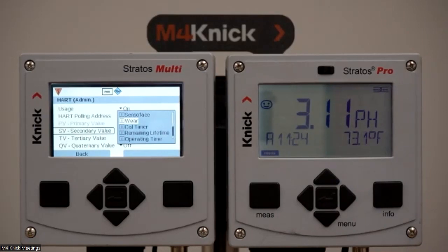You also see the smiley face, the well-known Senso face. Again, from a high-level, very simplistic diagnostic standpoint, this gives us a visual indication into the health of our electrode that's connected to it. There are three phases to that, right? So if the Senso face is smiling, all is well. It may turn to a neutral face or a flat face. That would indicate that you want to attend to that particular sensor soon. And then, of course, it can turn to a frown face, which means attend to that sensor now.